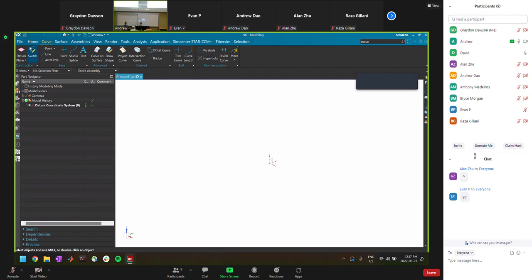Essentially, instead of having your one sketch feature where you're dimensioning in XYZ, in NX you have to set up datum planes, different planes where you have things positioned, and then do your lines from points to points. So the curve section is essentially your 3D sketch in SolidWorks. Again, each of the things has a little drop-down menu of more features, and at the end there's a bunch of other features.